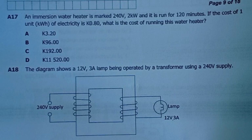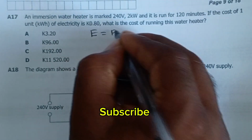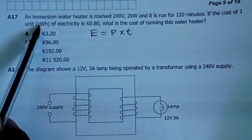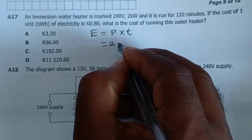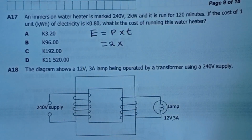So the first thing that we are going to do is find the total number of units which were used. So the total number of units is simply energy. So energy is equal to power times time taken. Power must be in kilowatts. Time must be in hours. So number of units is equal to power, which is 2 kilowatts, times time. Time, we have 120 minutes.